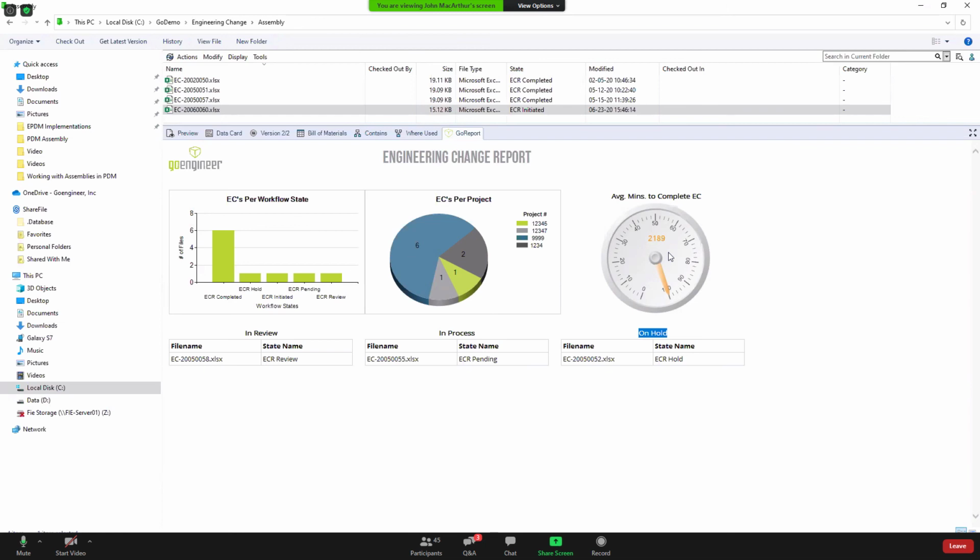Frank Root has a question: you have PDM and you're still having corruptions. We were talking about file corruptions, John. Would that be a support call, to try to get someone online with them? Yeah, it'd probably be a good idea. Off the top of my head, if you're still seeing file corruption, I definitely want to look at whether or not it's PC specific. If one user, one PC gets more corruption than others, I'd be suspect of the hard drive. If we're talking lots of different users, then there's something more at play.